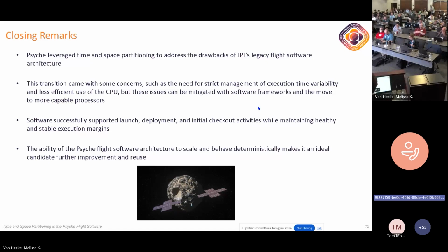So we didn't completely write it ourselves. It's based on Green Hills INTEGRITY. There are some institution-specific modifications, but we use their partition scheduler. We did look into a fully ARINC-based OS. A decision was made early on because the way to do things in that architecture was pretty restrictive. I wanted to leave the freedom to possibly change the architecture.